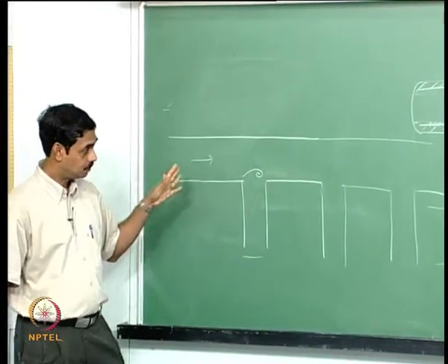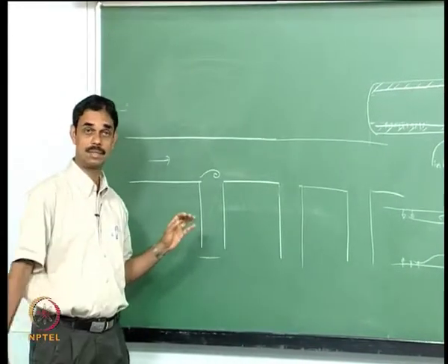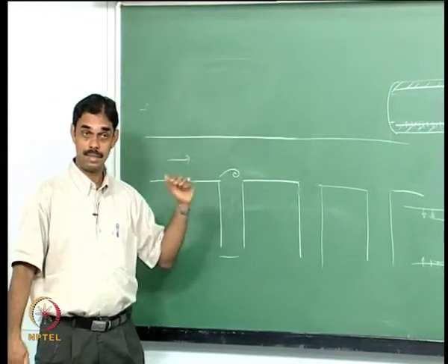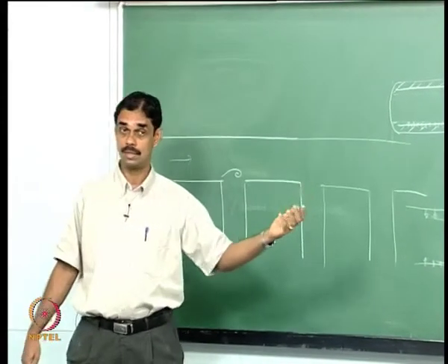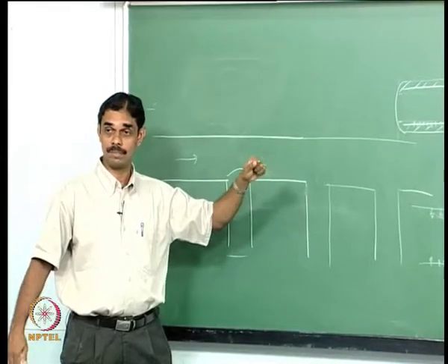The ducts are very long and the vortices are strong, so they can travel long, and the sound wave will travel quite long, and as any sound wave travels, as will be discussed, it will steepen into a shock, so you can have large amplitude shock waves coming and rupturing these pipelines and so on.